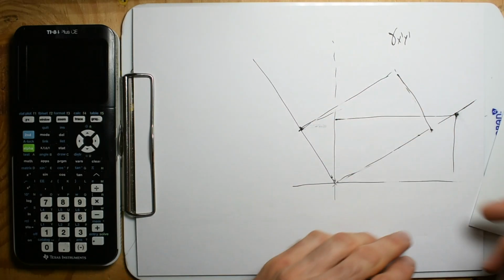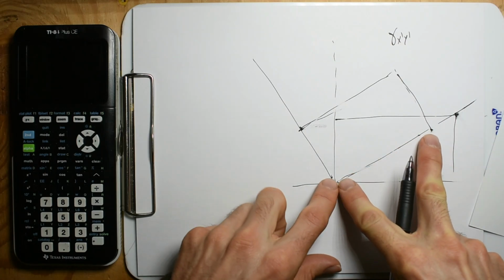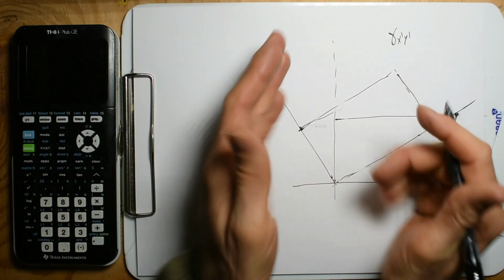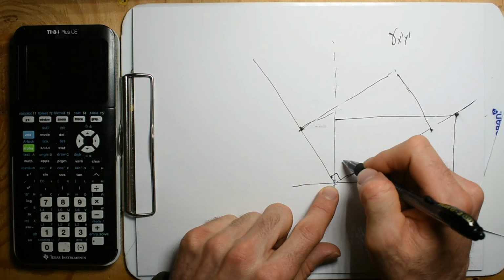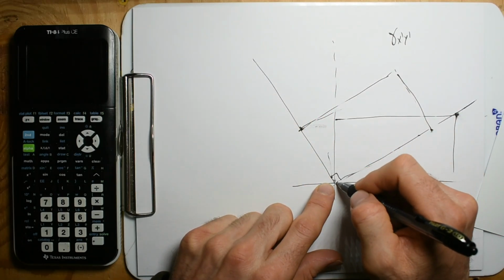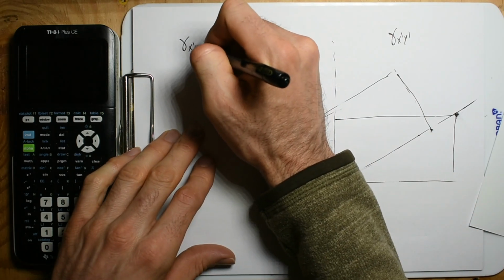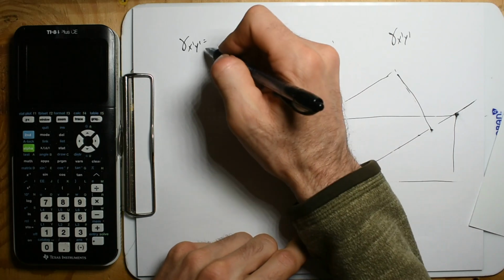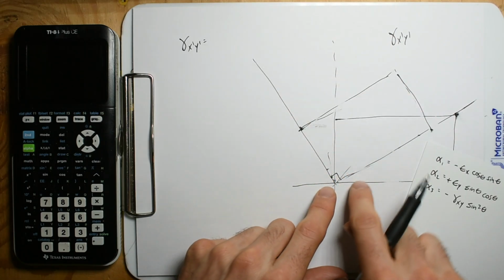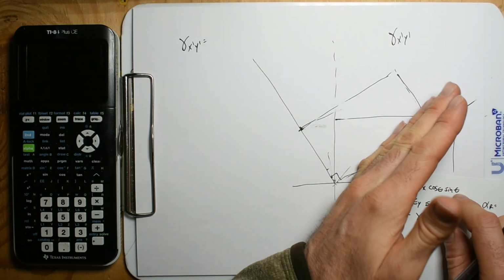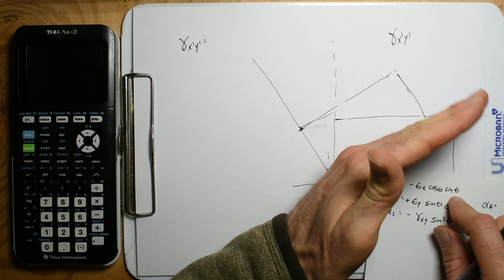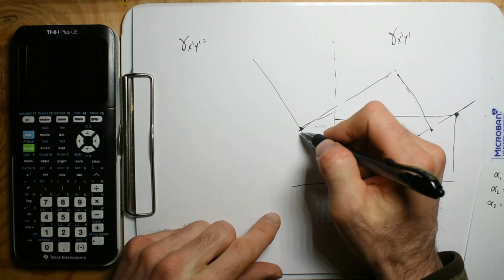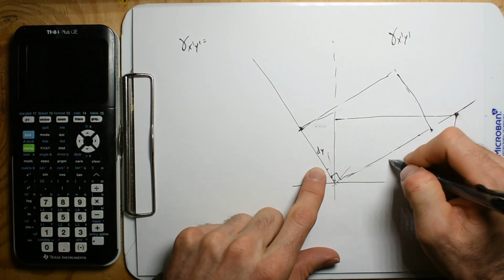But that's only a partial of what the shear is. The shear is going to be the reduction. This is a 90-degree angle. The definition of shear is going to be the total reduction of angle. So alpha is going to be the reduction of angle on this side, or increase. It could be a positive shear or a negative shear. But now we have to come over here to do this diagonal. So this is dy, this is dx.